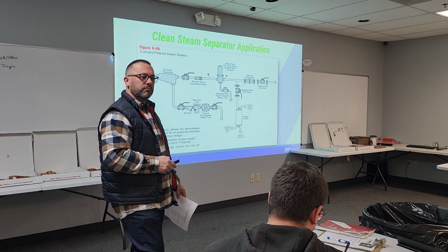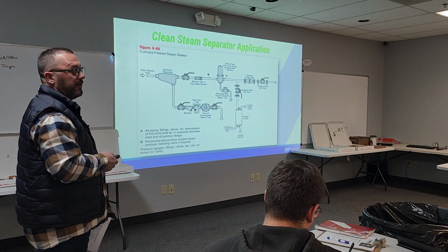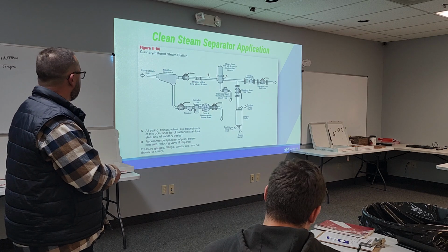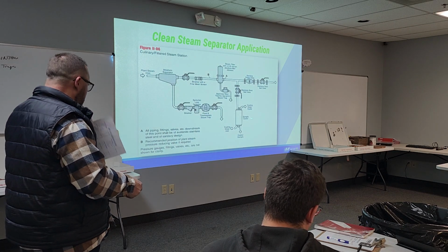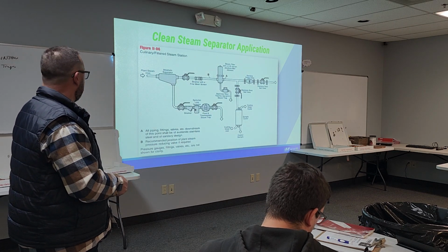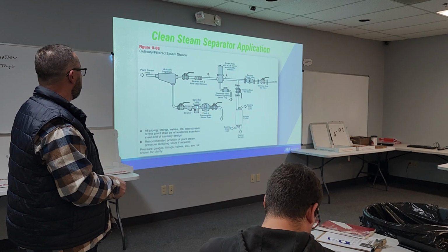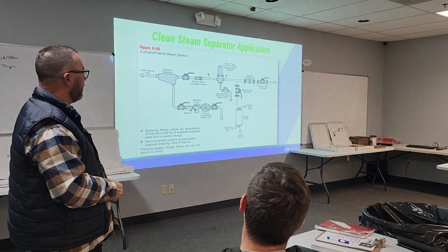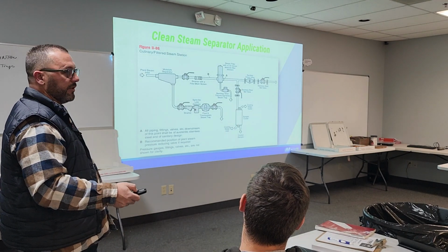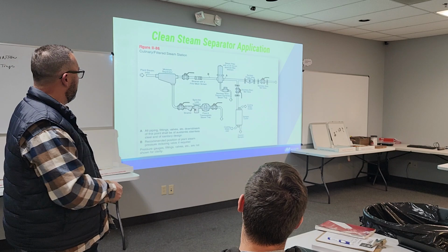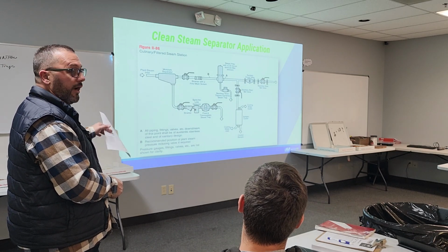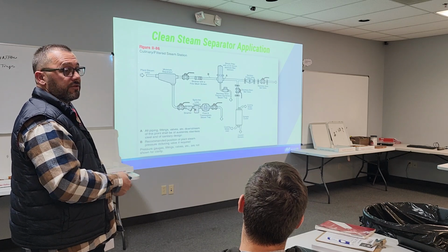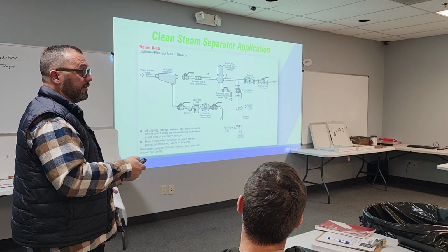What's the loss detector? The loss detector detects if the steam trap is blowing through. In this case, this is kind of like a Spirax Sarco hookup, really from that hookup book. And really what it's doing is just detecting if any steam is blowing through, and then it would give you an alert. Of course, we've come really far in that technology now, where these no longer are a wired thing hooked into a control panel. They're actually wireless.